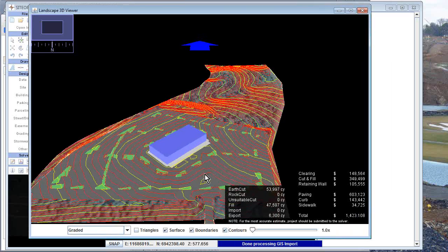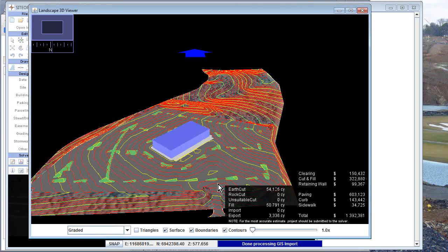If I turn the contours on, you'll see them all twinkling. That means they're thinking. They're trying to calculate the cost to be a low-cost scenario, and I'm trying to balance the site. Now you'll notice I've moved 54,000 yards of earth to build this site, but I'll end up with maybe 500, 600, 700 yards of export at the most. So I think we can agree that this is a balanced site. If I submit this into the cloud for high-level processing, which is included in the package, I will start to approach zero even better than I am now.